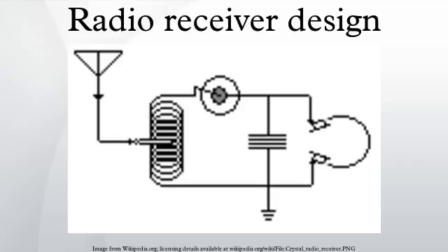Regenerative. The regenerative receiver also had its heyday at the time where adding an active element was considered costly. In order to increase the gain of the receiver, positive feedback was used in its single RF amplifier stage. This also increased the selectivity of the receiver well beyond what would be expected from a single tuned circuit. The amount of feedback was quite critical in determining the resulting gain and had to be carefully adjusted by the radio operator. Increasing the feedback beyond a point caused the stage to oscillate at the frequency it was tuned to.